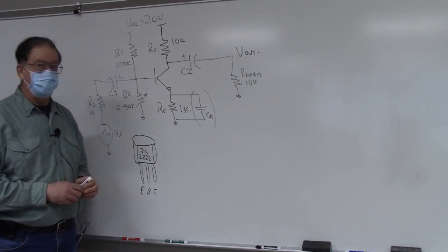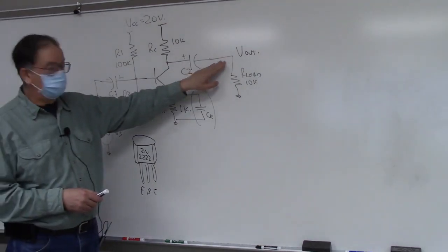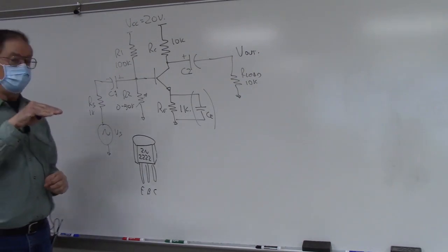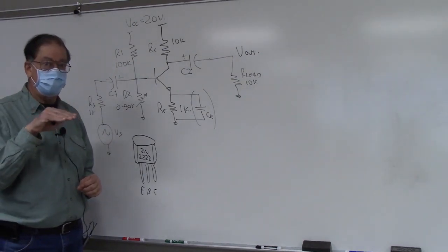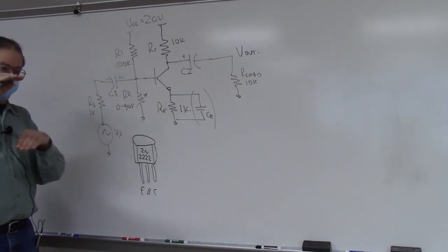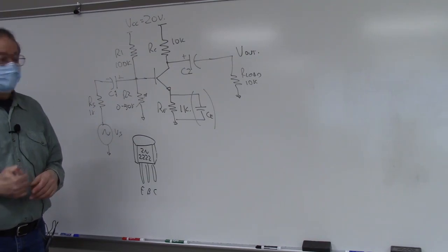So we're going to measure dynamic range. We're going to turn up VS until we start to see distortion on V out. As soon as we get the first sign of clipping, we're going to hit our limit for what's called symmetrical dynamic range. But then we'll continue to turn VS up and get the total peak-to-peak dynamic range. So we'll have 2 different values for dynamic range.